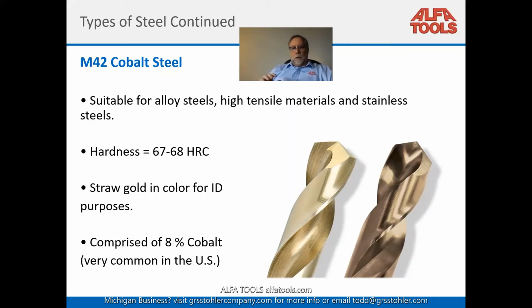So colors, you know, when you guys are out there and we're looking at an end user's tool crib or a drawer full of tools, or just talking to a customer and he says what he wants, if he says cobalt, if it's a cobalt jobber, you're done. Just find out the size. You don't have to worry about the points, because cobalt are all the 135 split. So what do we have next?